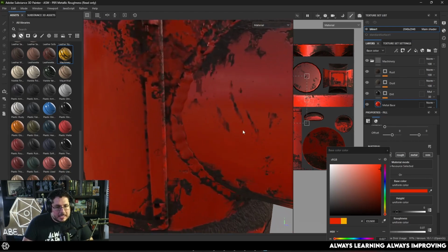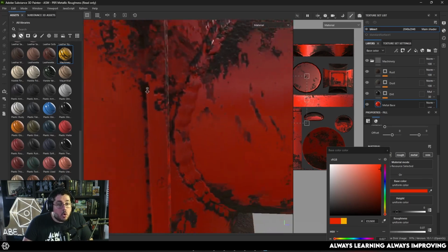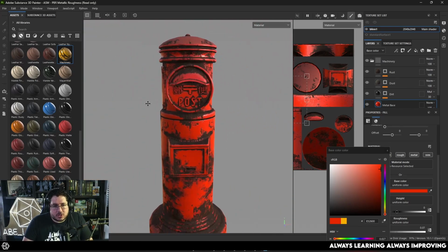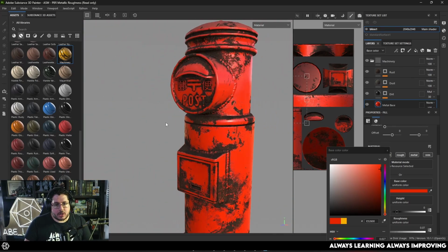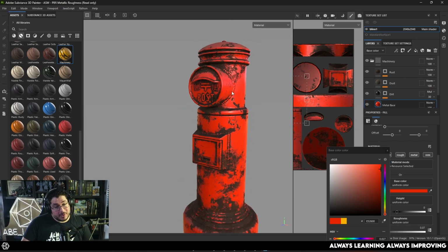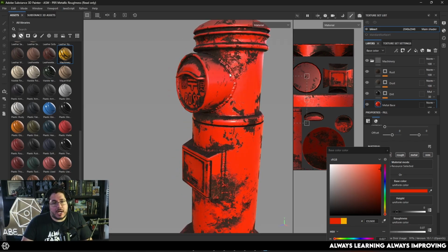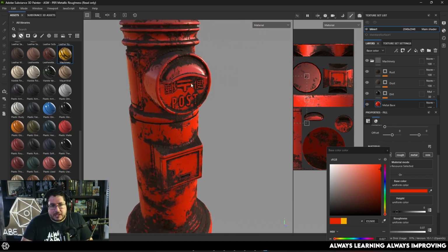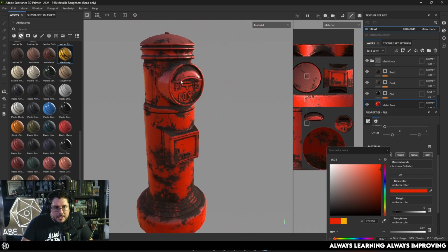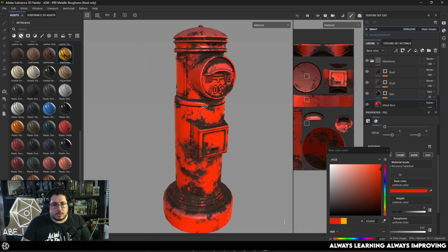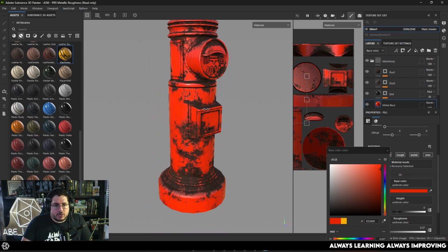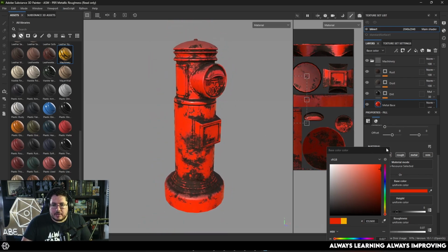I don't think it's an extremely horrible thing to see, and as you can see, with texture it gets hidden. The only way to solve that is by either creating a weird normal movement on the faces or just merging everything together. If we merge everything together and we soften that edge, it could be with a boolean, and then just triangulate everything. That's fine. It's also going to increase our poly count a little bit. But hopefully with this video, guys, you get a nicer idea on how we can deal with these elements.